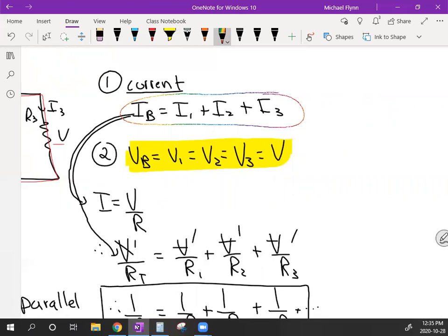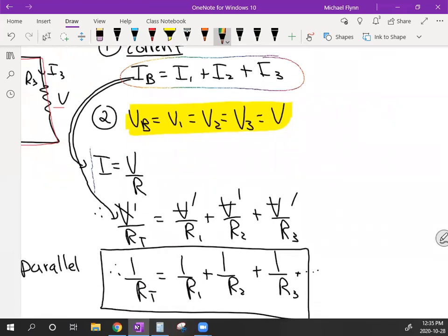All right, now I'm doing a little math. The current in Ohm's law is given by V divided by R. So I'm going to take this equation that you see circled, and I already put an arrow down here. I'm going to replace all the currents with V over R. The battery current will be replaced by the voltage in the battery divided by the total resistance in the circuit, because the battery acts on the entire circuit, if you like.